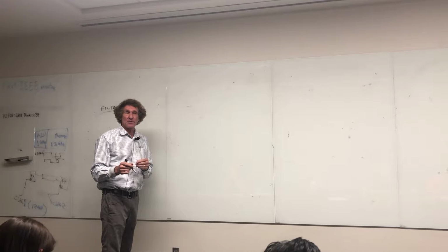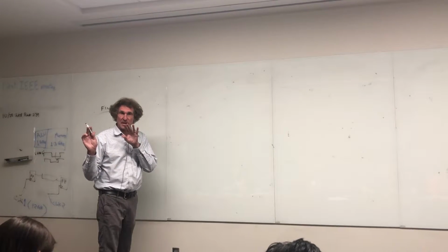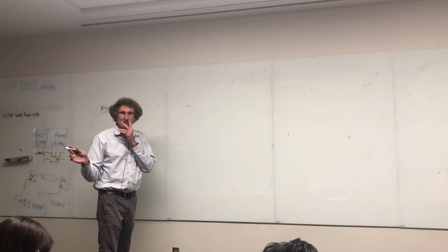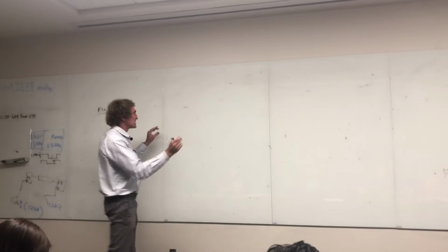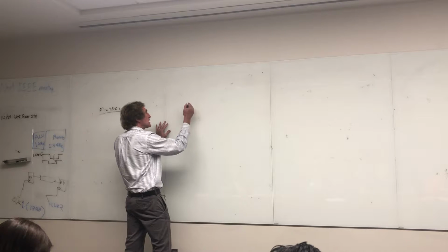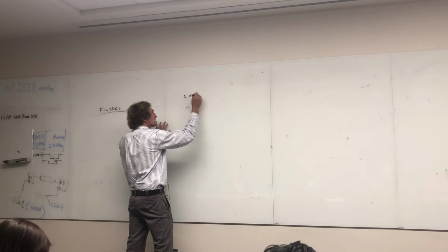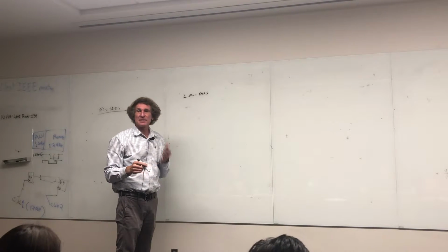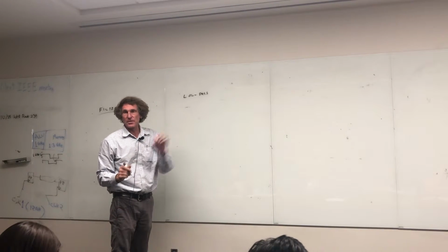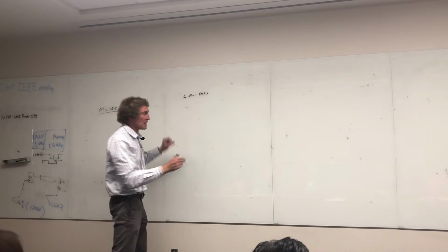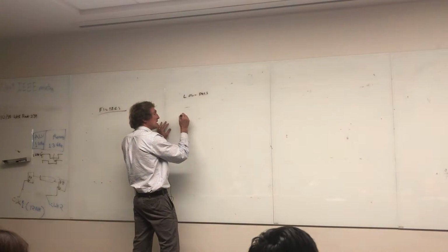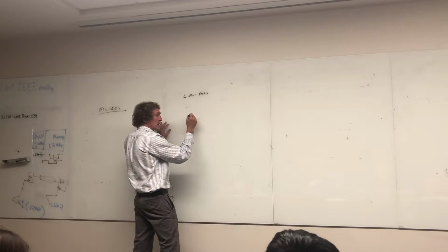The thing about an analog filter, it's dirt cheap. So remember that. It's dirt cheap to do these, and they work for most applications that are fairly low frequency, not high frequency. So first we talk about two types of filters. The first one is low pass. Most of you are familiar with that. Low pass means the lower frequencies are going to get through the filter and the higher frequencies are going to stop. So the standard way to do this, if you want a low pass, you can do it this way.